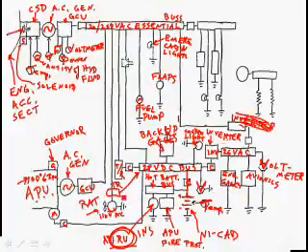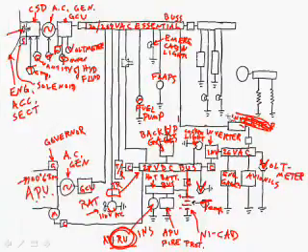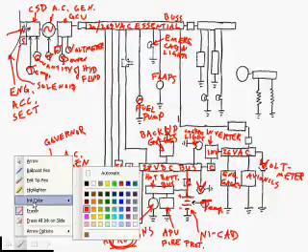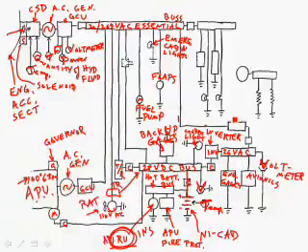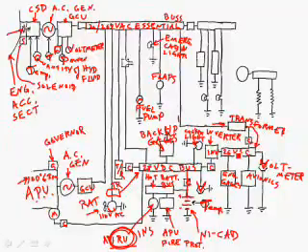Boy, that was incorrect. Sorry. I hope you're not doing this in ink. We can do it with a step-down transformer. We can allow high voltage alternating current in, and through a contactor we can feed this low voltage AC bus, so it can get powered in flight without having to take power off of the DC bus.